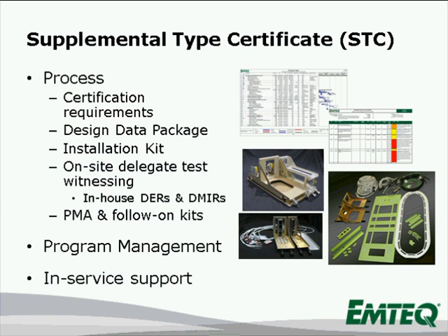We also develop an installation kit, which consists of some of the provisions that you see there, all required wiring harnesses, coax cable assemblies, and any mounting trays for the equipment. Some CMU mounting trays and VHF mounting trays are shown on the left, as well as the structural components that would be required to mount an antenna or any other mechanical items in the aircraft.